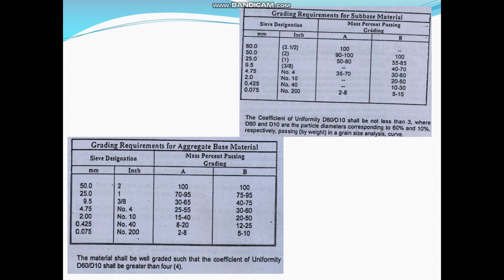Now there are certain limitations against which we have to perform the gradation. You must have performed the same experiment in the geotechnical lab, but the purpose of gradation or sieve analysis there is to see which sizes of material are present in our sample. But for transportation engineering, when the aggregate is to be used in a road pavement or say an embankment, then you have to gather material according to certain specific sizes. For instance, if I say that there has to be at least 25% material on sieve number 4, then that means that a certain mass needs to be gathered together to be put in the pavement or any structure that you are going to construct.